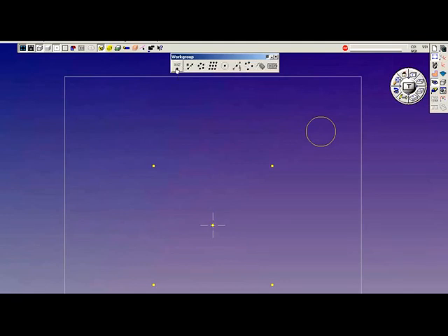and generate a center point. Point tile, point creation subpalette, select center point, click on the circle to identify it. You see the label here. For viewing reference labels, Control L will activate labels. And I see a C1 here. When I selected the circle, the reference appeared in the C text input. I hit the single circle tile, and I get a center point referenced as 0.6. 1, 2, 3, 4, 5, and 0.6. Circle 1.